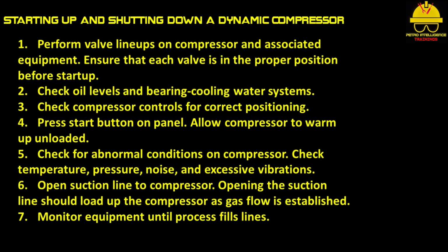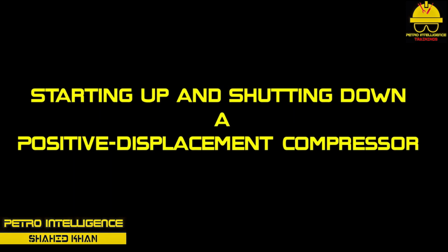6. Open suction line to compressor. Opening the suction line should load up the compressor as gas flow is established. 7. Monitor equipment until process fills lines.